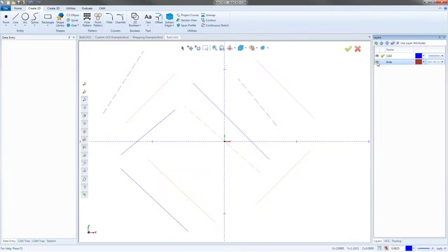So anything that was drawn while the check mark was on the lines layer is on the lines layer. Anything that was drawn after we put it back on, like the CAD layer here, all went to the CAD layer. So again, you can move these up and down. You just pick them, you just move them, and now they're switched. There's your delete function. And then again, there is the use layer attributes function. So you have that ability.